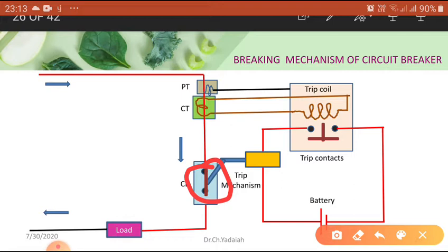If external pressure is applied on the bubbles, then the rate of deionization of the ionized gas medium increases, which leads to an increase in the dielectric strength of the medium between the contacts. So this is what happens by using this gas.